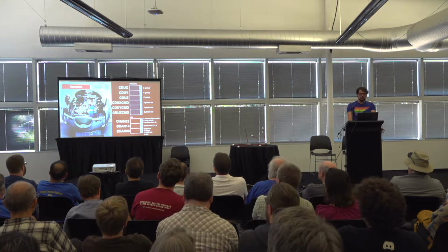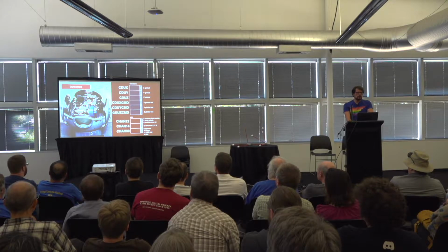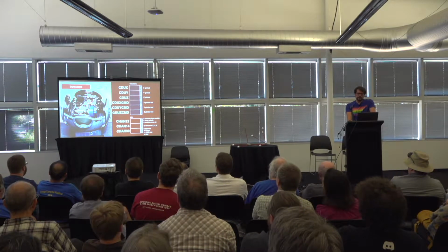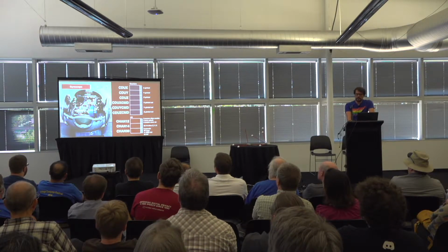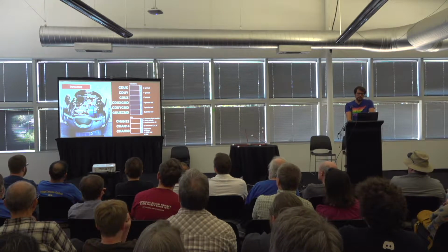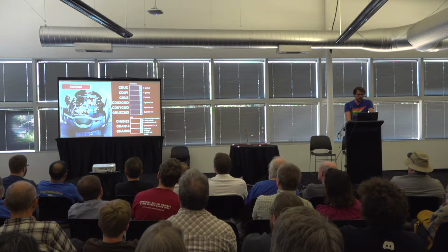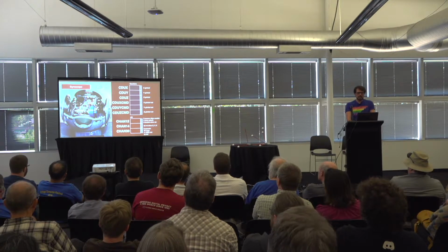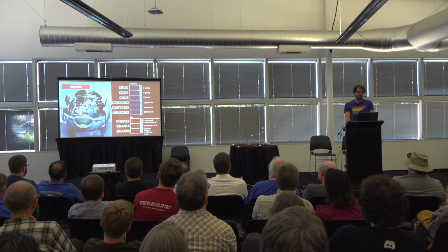The gyroscope is the core peripheral that the AGC was originally built around. The AGC rotates it into a certain base position with the CDU-CMD counters, and then the gyro detects rotation around the 3 axes of the spacecraft that can be read from the CDU counters. Using the gyroscope, the spacecraft always knows its attitude, which is its orientation in space.